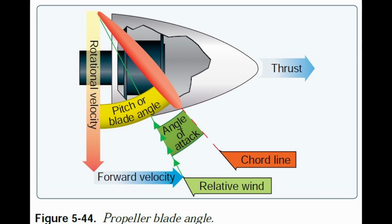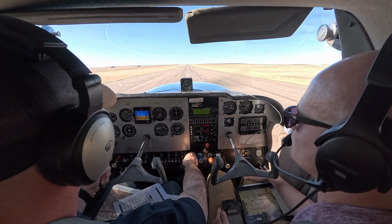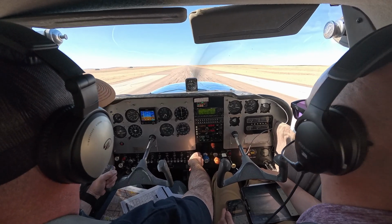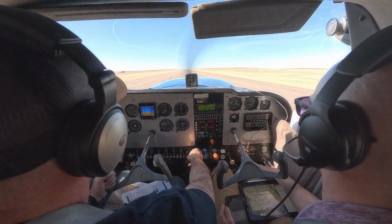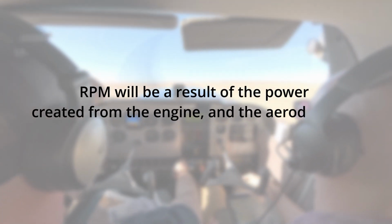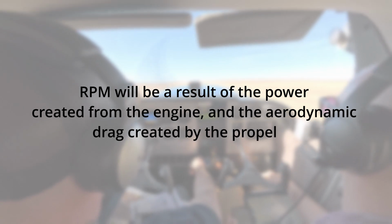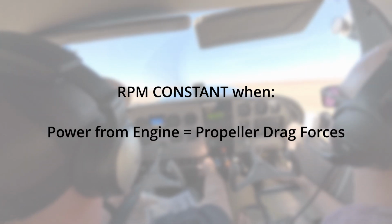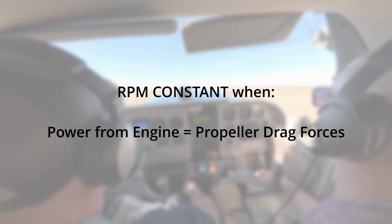Since the propeller is a rotating wing through an air mass, it's important to remember that our propeller is always producing drag on itself. For both fixed pitch and constant speed propellers, the resulting RPM on a propeller will always be determined by a balance between the power created by the engine and the aerodynamic drag created by the propeller. When in balance, RPM remains constant.